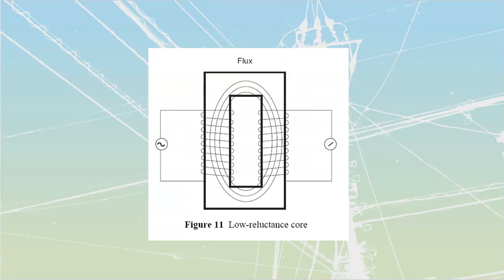What we can do is confine the flux lines by putting them across onto a single core over here. And when we place them onto a single core like this, we hold onto all of these lines of flux. That core is going to maintain all of our magnetic lines of flux together. That way we're going to have almost all of the lines of flux that are created on this side cut through on this one. So we're going to have a very efficient transfer of voltage from one side to the other. Here's how it works.